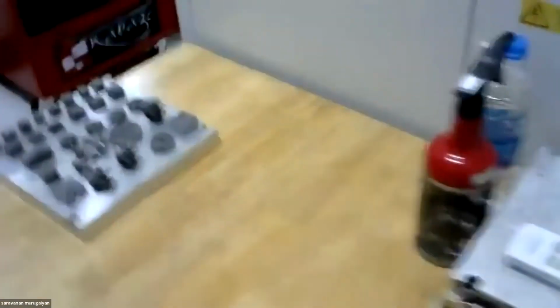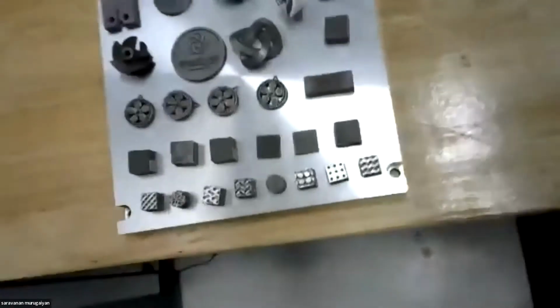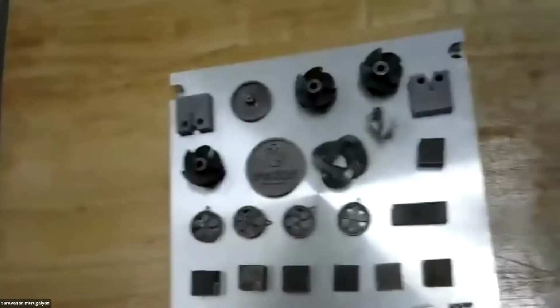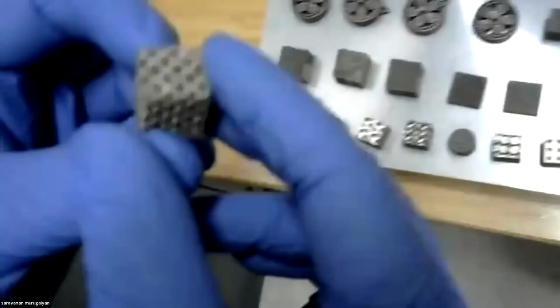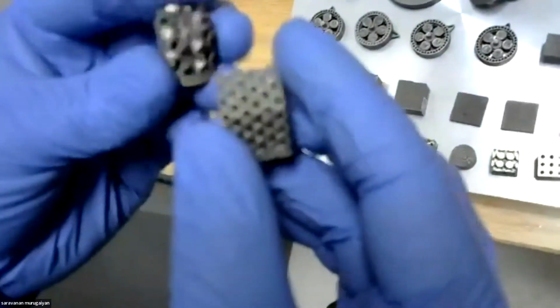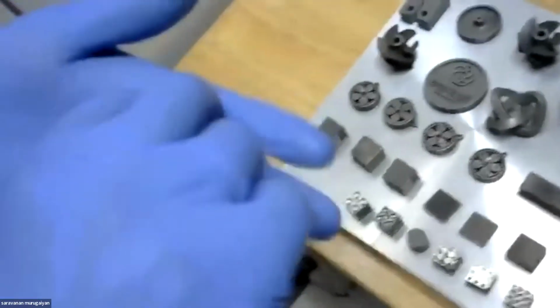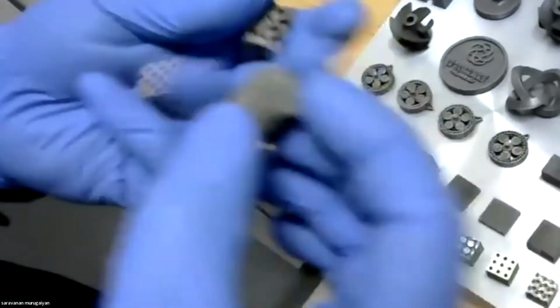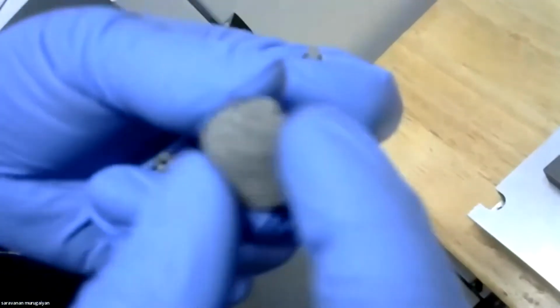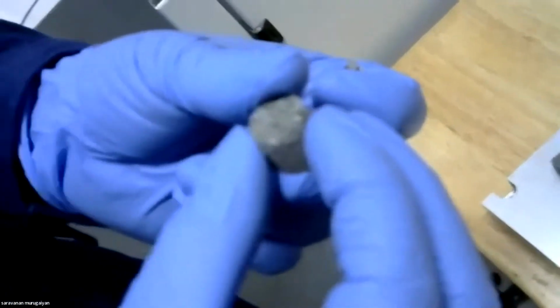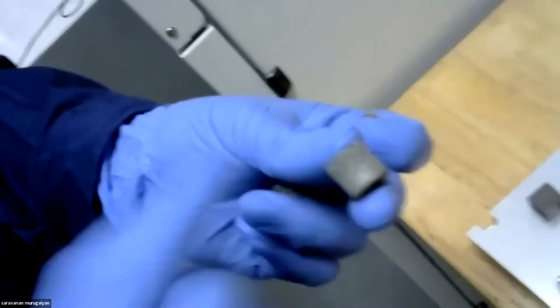And for the last part, I would like to show some of the parts which we have printed. We have printed a lot of parts, but a few parts we have kept to show the capabilities of this machine. You can see these are some of the porous structures which we tried to print. These are lattice structures. We even tried to print a few bone structures also. These are cylindrical coupons on bone structures ranging from 100 microns to 300 microns.